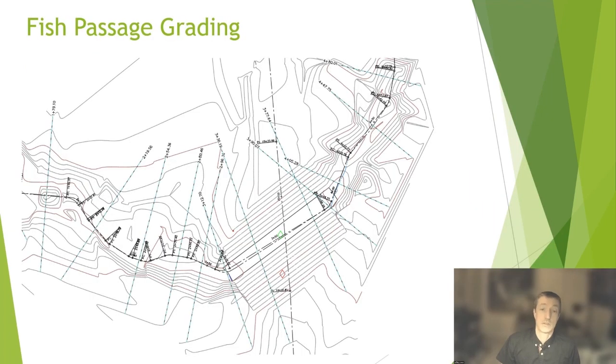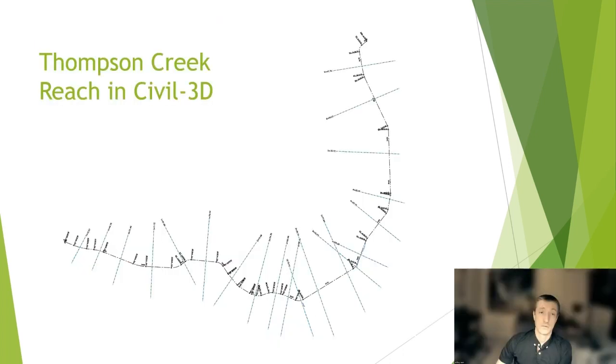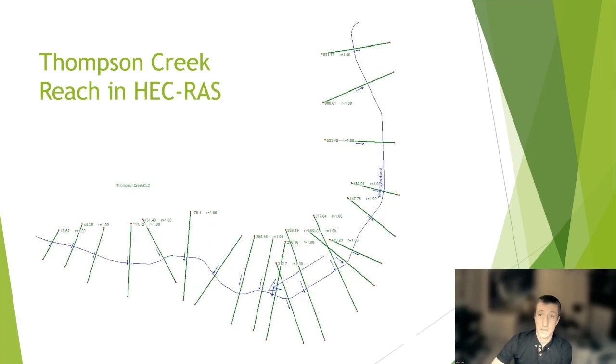To test the hydraulics of the proposed site, a combination of Civil 3D and HEC-RAS programs were used. Using the topography that was provided by the client, a post-excavation drawing was created using the 2-to-1 slope ratio grading that was agreed upon by the team. A reach of Thompson Creek was created using an alignment through the newly made stream bed profile, and sample lines were formed for the basis of the cross sections. This was then exported to HEC-RAS for analysis.